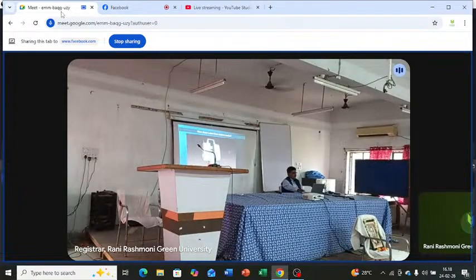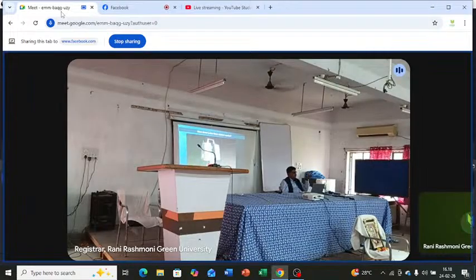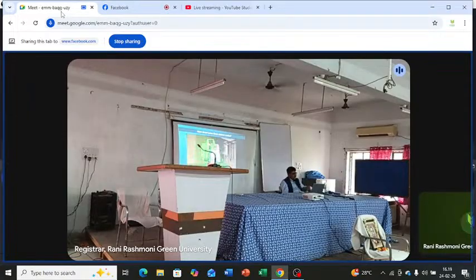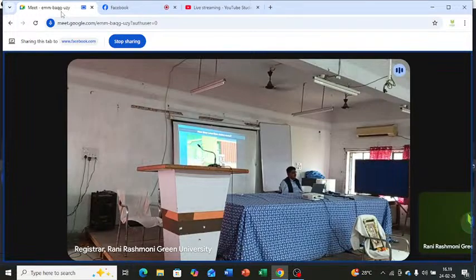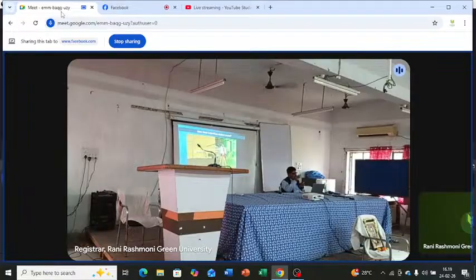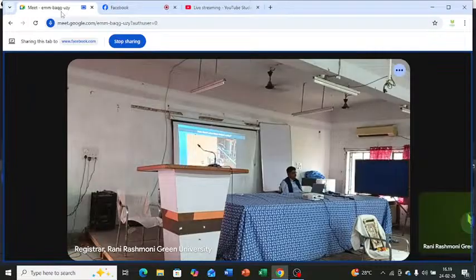So how does it actually work? A little background story. It produces a laser which is reflected by this prism mirror, and the mirror is also rotating. So a burst of lasers is generated, which gets reflected from the objects, and those are seen. For each and every reflected object, the distances are measured, and then it is plotted in 3D. And you finally get the coordinates of each and every point.